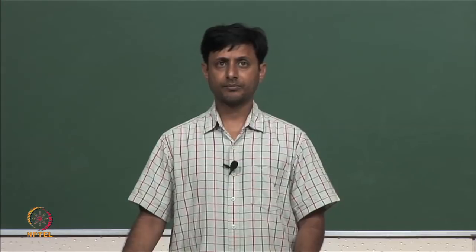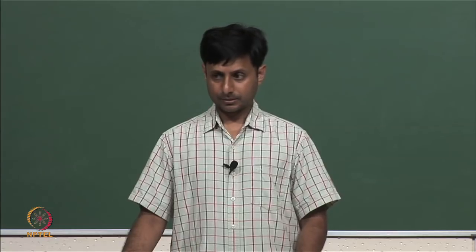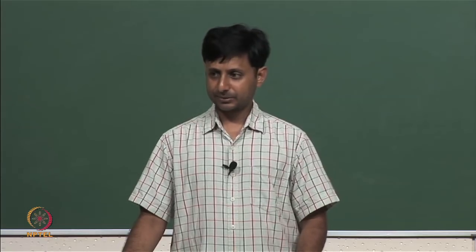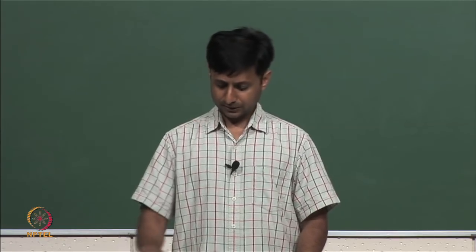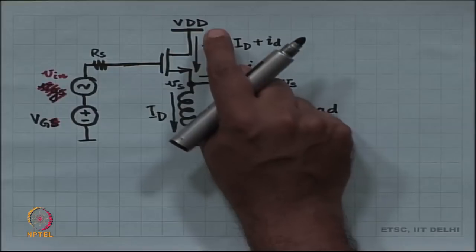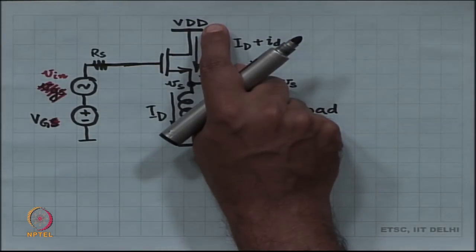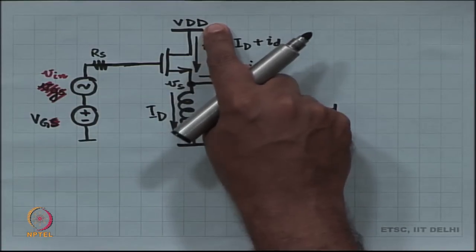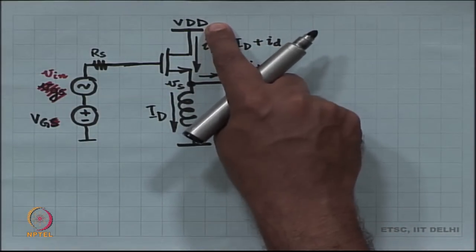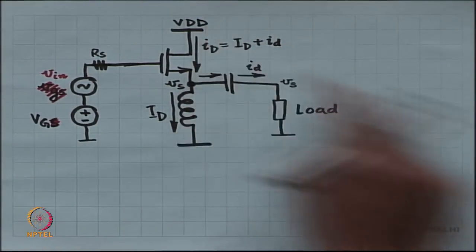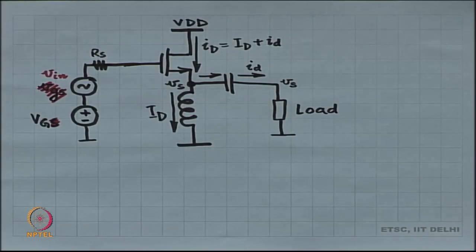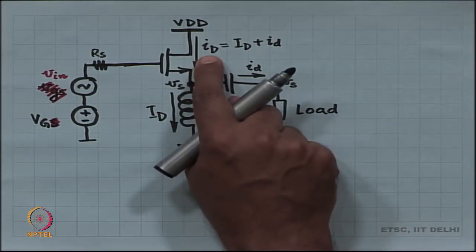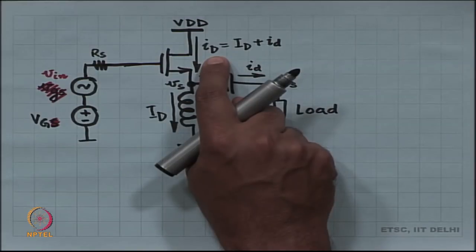Now, how are we going to do that? We are just going to first look at what is the power supplied by the only source of power over here. It is VDD times small i sub capital D. All right.